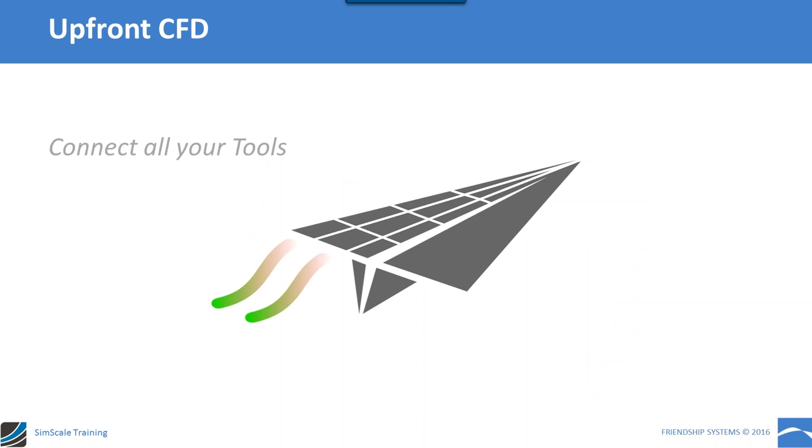Okay, perfect. So now we have talked about this technique of creating a model. You can create a fully parametric model by starting from scratch with your lines, or you can modify an existing model, like we have seen in these few slides of the LMP1 model, where you just apply this technique of morphing and form deformation, and you will change the geometry in the way that you want.